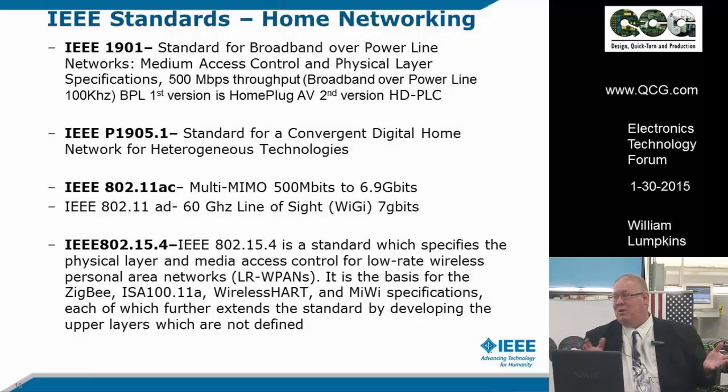The interesting thing is it's not new. It's been trying to take off since about '98, and they keep trying to reiterate over and over again. They've had lots of different early problems with doing Ethernet over power lines. If you came to a circuit breaker, as soon as it tried to jump the circuit breaker, your bandwidth would go from 500 megabits down to 10 megabits. It was just a huge drop. So they started to insert OFDM encoding methods, which fixed that problem. So now they're past most of those problems, and now it's very viable and very usable.